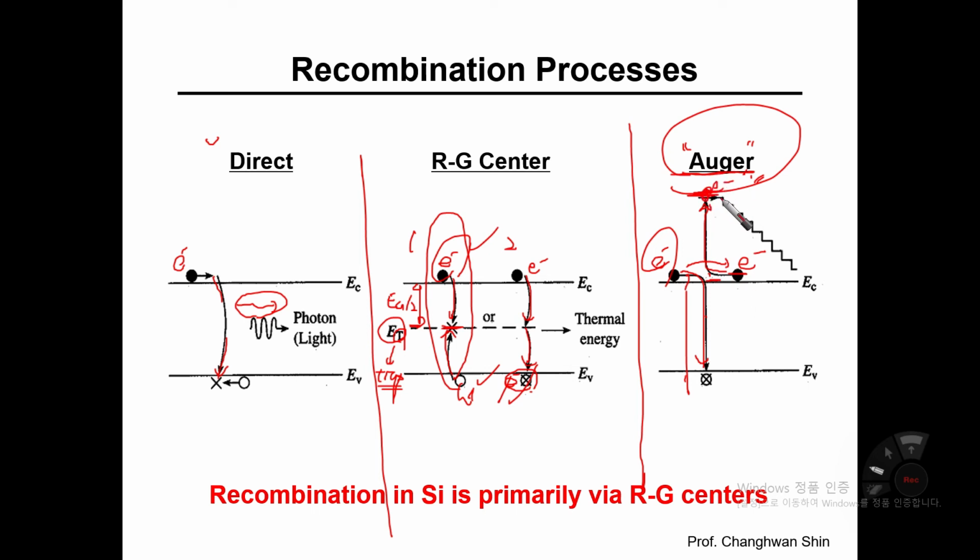Afterwards, this electron is going to move dynamically and roam around in the conduction band, and in the end, it's going to lose its own energy and go back to its original energy state. In this process, a lot of thermal energy is delivered to the outside. This whole process looks slightly complicated, but it is named the Auger recombination process, and it is how electrons in the conduction band can create a large amount of thermal energy.